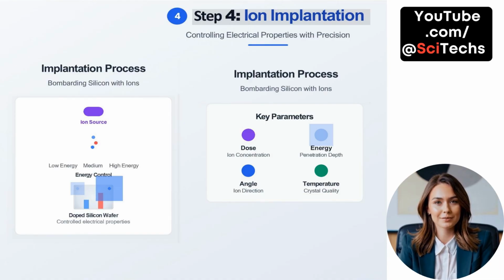Implantation process. Ion implantation modifies the electrical properties of silicon by bombarding it with high-speed ions. These ions are sourced from a controlled ion beam, and their energy levels can be adjusted, ranging from low to medium to high, based on how deep the ions need to penetrate the silicon wafer. The end result is a doped wafer with finely tuned electrical behavior.